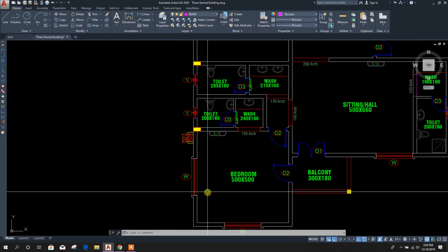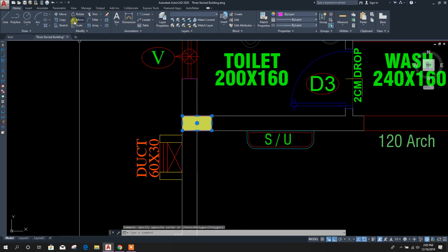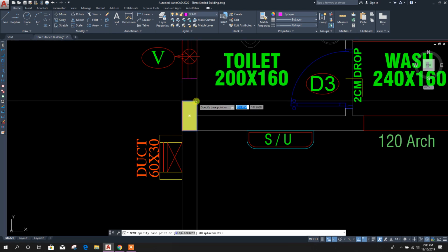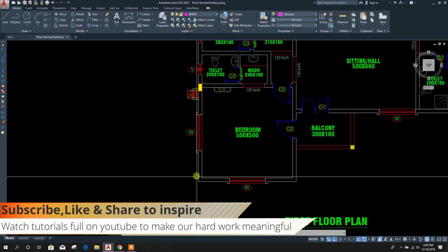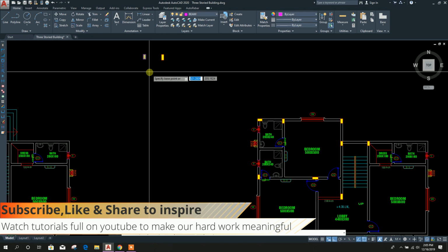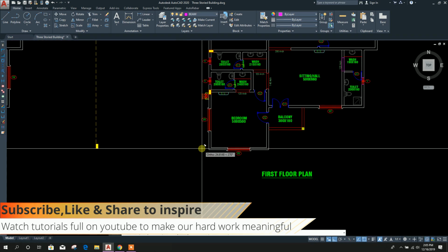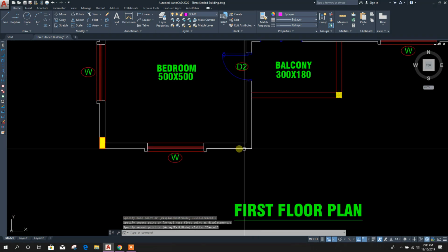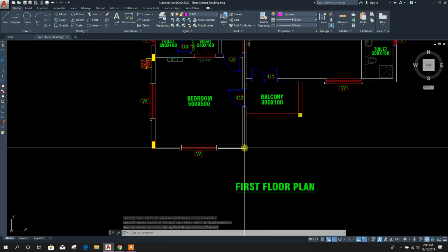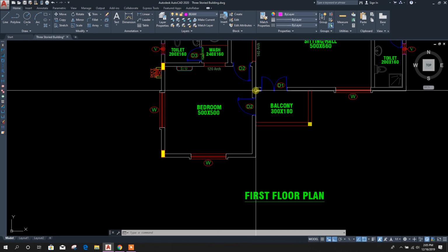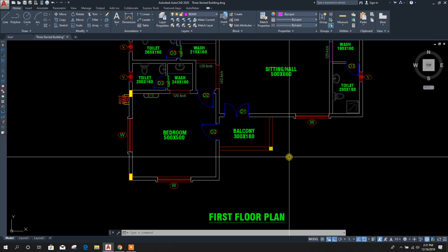Now in this side, here we can rotate this column to reduce our beam span length in this direction. Copy this one and here to here. Okay, now this column we can make it in other direction, and here we can provide one column.